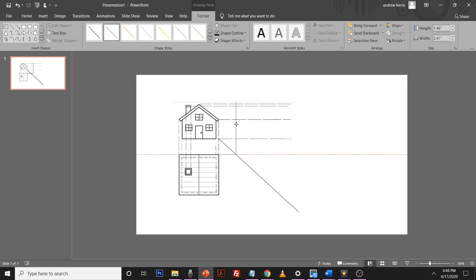There we go. Alright, so we'll just make a copy of that. Ctrl C and Ctrl V to copy and paste. Place it where you want it to go, and then extend your lines back to the original starting point. That's so. And let's see if we can stretch that to meet our 45-degree line, and stretch upwards to meet the end point. The lines may shift sometimes out of place, but you just have to move it around till it finds the right space.